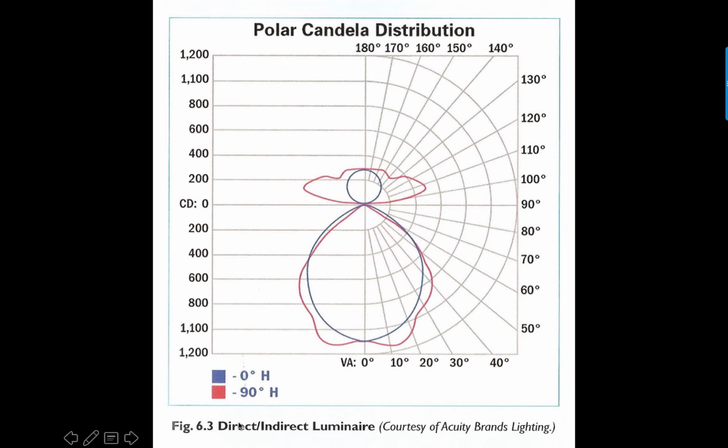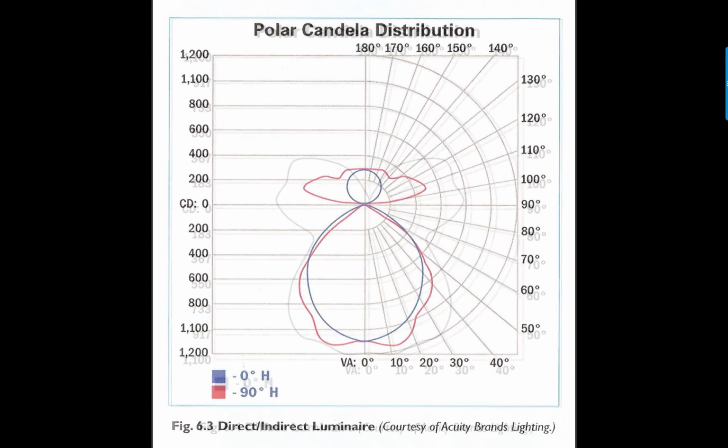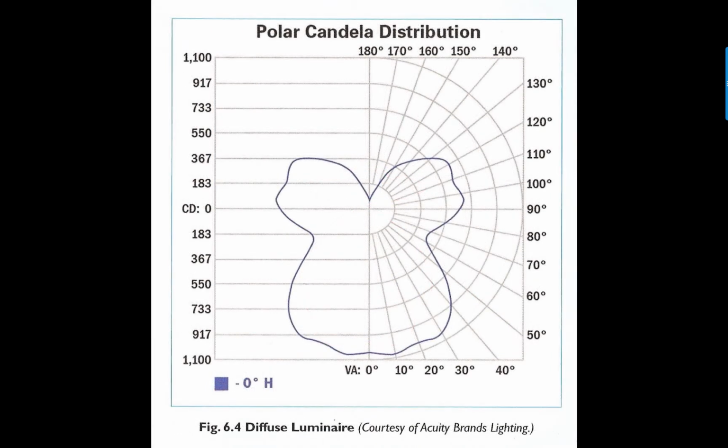And these are lovingly known as direct, indirect, and filter light fixtures, which is a little passive aggressive if you ask me. But anyway, the idea is that there are any number of different flavors of directionality of the light fixtures, and it's really up to you as to the effect you want to have. If you want a little lighting on the ceiling just to create a sense of volume, you'll want a little uplight. But sometimes you want much more uplight and less downlight if you have, say, a lot of screens in a space. Conversely, if you have a lot of visual tasks that are flat, like reading or assembling, I don't know, boards, then you're going to want more downlight.